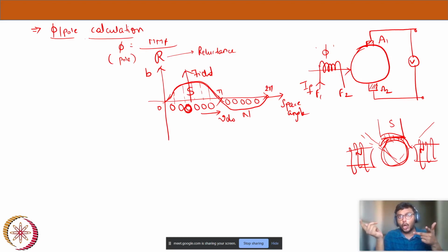When we come to the torque derivation, we will use the left hand rule, because the left hand rule will give us the direction of force, the thrust, the direction of movement of the machine. I will not suggest you remember it as motor left hand rule, generator right hand rule, but just remember the rules, and whatever component you want to know the direction of, you apply it. That's my suggestion.